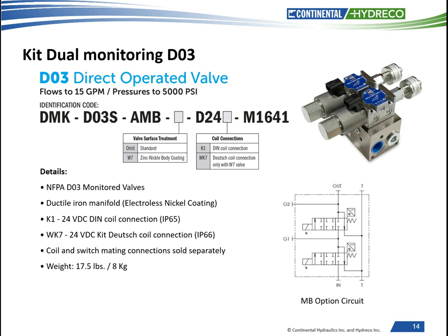The flow forces will act upon the spool. Typically, these types of products are derated in flow and/or pressure capabilities. So rather than being able to operate at 15 gallons a minute, they may be limited to 8 to 10 gallons a minute, and pressures may have been reduced as well.